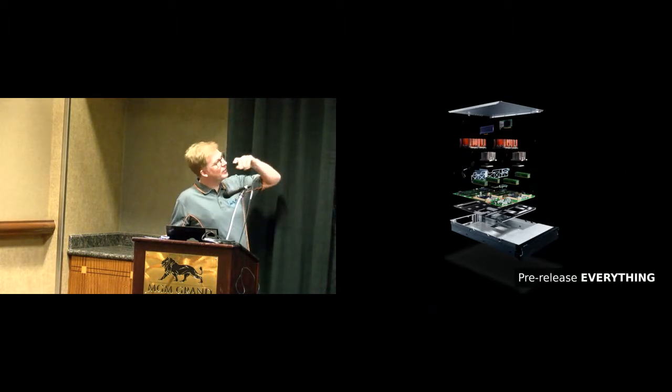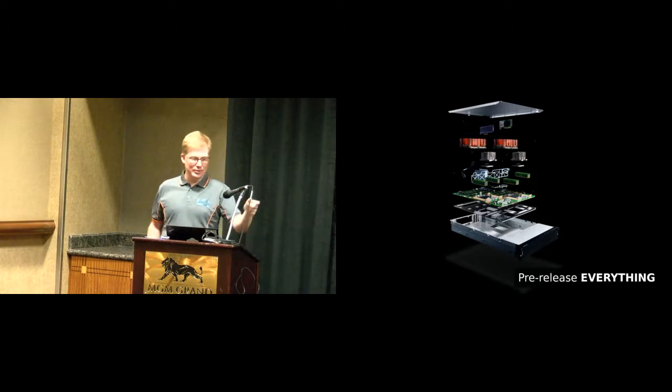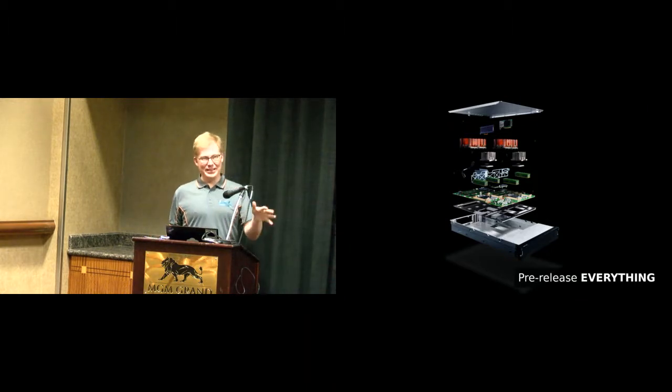The BMC, we've got a little BMC card off the side, so it's on board on the, I was going to say Zaius/Barreleye G2, but other systems it's a plug-in one. And we had new hardware on the BMC, so a new AST 2500, as well as OpenBMC, so a new BMC firmware stack. On P8 we had an AMI or Supermicro-based BMC stack, depending on the machine, and in P9 it's now OpenBMC on Witherspoon, and we still have AMI and Supermicro-based BMCs as well. But with an open source BMC stack, things are going to be different, right? It's not exactly the same as we've dealt with before.